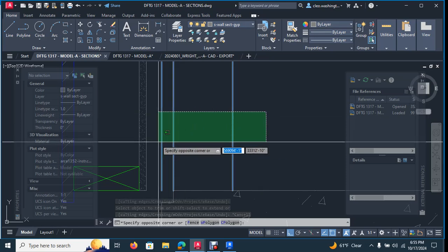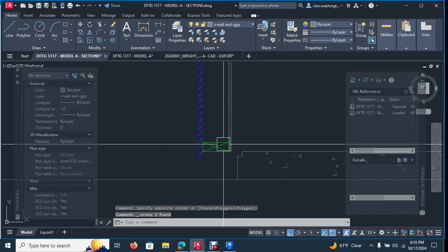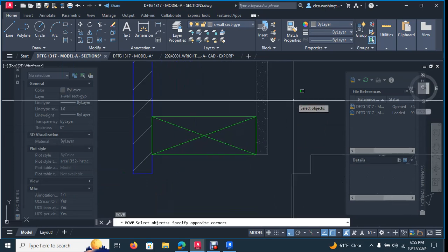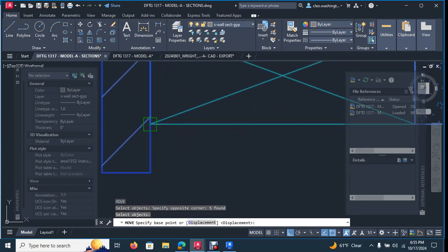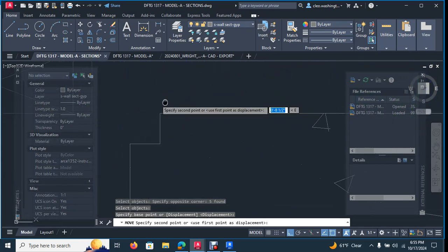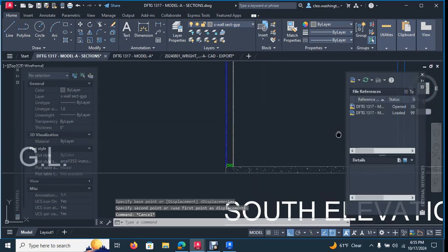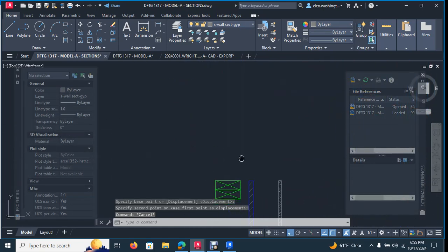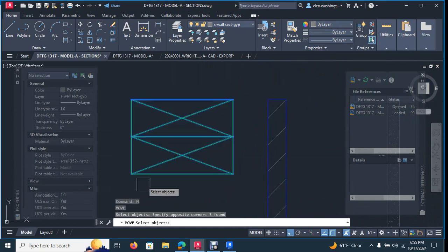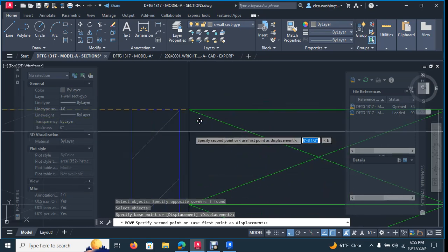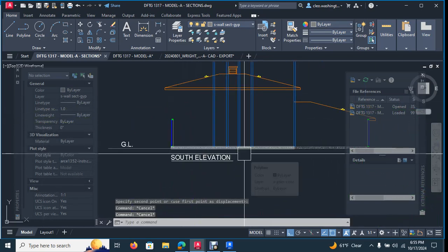All right, so now you can take this line and just delete it because we've already drawn it. Delete. And you take this guy and you just go ahead and move it in. Now typically there's a damp proofing membrane that goes in here, when we draw our wall sections and stuff like that, that's when we'll get into more of those fine details. But right now, we just need to show the contractor what the building looks like, okay?